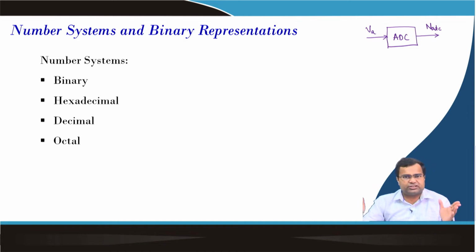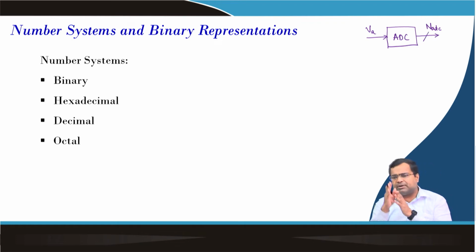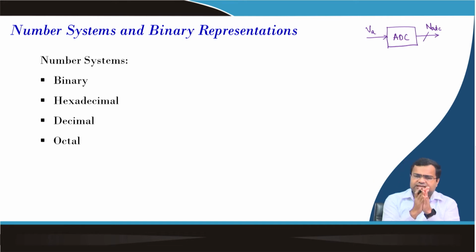So, the conversion process takes time, but you can also have a parallel ADC where the number of lines can be parallel. So, you will get the data in parallel, that means it can be 8 bit, 10 bit, but here the number of data lines will increase. So, as a result, when you talk about a digital platform, you need more pins of the digital circuit to accept that parallel data from the ADC.